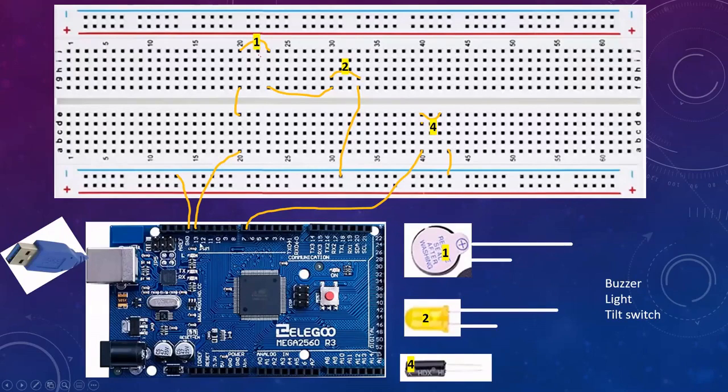As a quick review, when channel 13 is being turned to high, the electricity is traveling all the way through and back to ground, making an alarm sound. And we had turned that on and off with the tilt switch, which was being fed into digital input number 7.